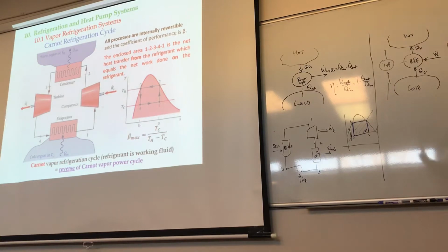But theoretically, in the beginning, since we don't know much about this, we're saying that we are ending as saturated liquid, right? But still at high pressure, right? So if we go saturated liquid at high pressure, I come in here and throw it through the turbine, which is not a good idea to start with, right? You get a bunch of liquid that you're expanding through the turbine. And then you generate theoretically some little work, and then you're going from 3 to 4 isentropically. Now you end up with really low quality, right?